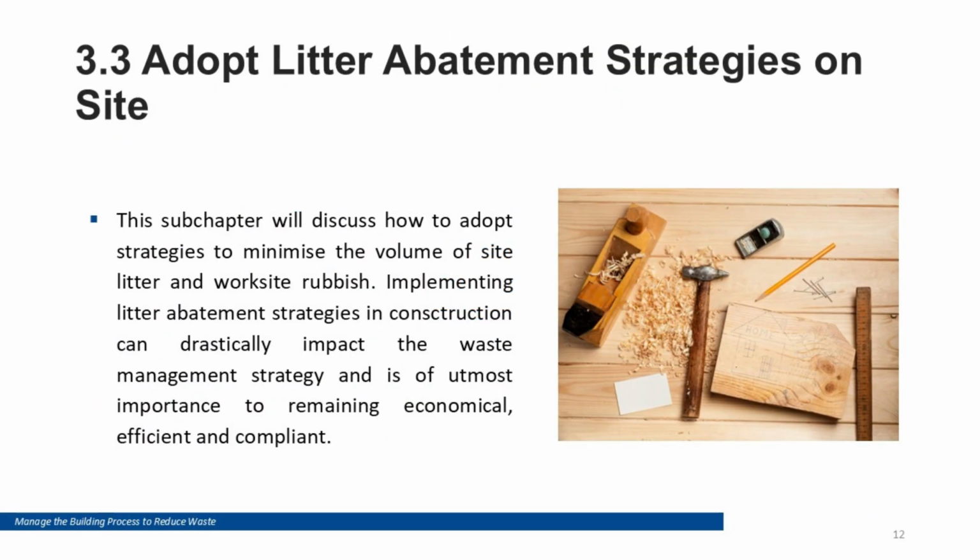Litter control protects the environment, the public, and site safety. Practical litter abatement includes covered bins and secured skips, clear signage and designated disposal points, regular site housekeeping and clean-up routines, and managing wind-blown materials and loose packaging. Contractor responsibilities built into contracts.